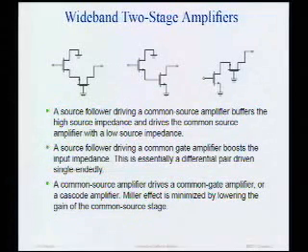All right. Another way to build a useful two-stage amplifier: one of the big problems with our common source amplifier was the Miller effect, right? And we mentioned that if you have a low source impedance, Miller effect's maybe not too bad. Well, one way to generate a low source impedance is just to buffer the actual source impedance.